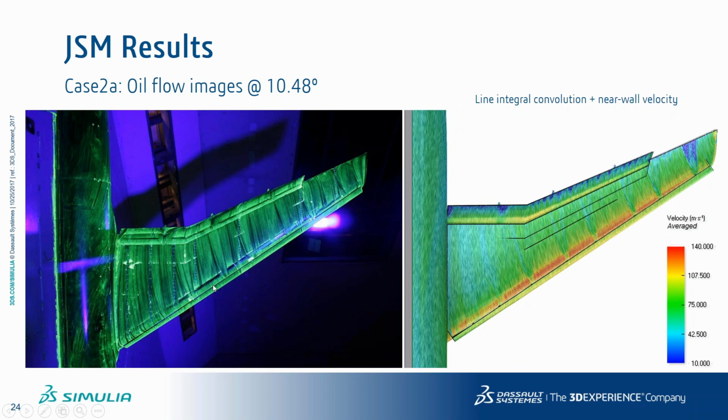All these are due to the slat track fairings, which are the small elements that join the wing and the slats. Of course, they are below on the pressure side, but still they affect the flow through the gap. That's where we say the gap is important in the high lift devices. They also affect the suction side, and you can see the flow impact on the suction side from those devices that join these elements. So we can see they're aligned pretty well with what we can see in the wind tunnel at different wingspan positions. This is for 10 degrees, so that's a very moderate flow angle.